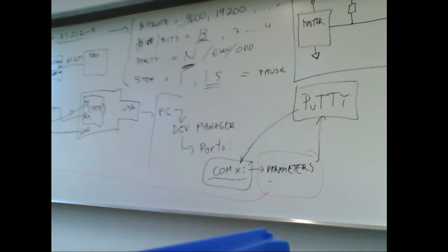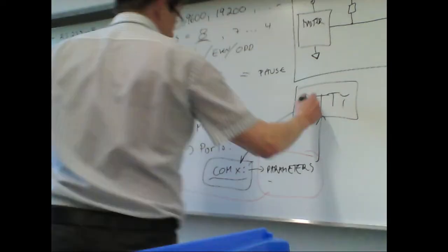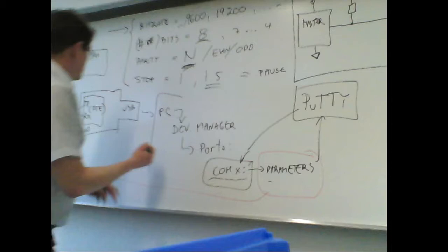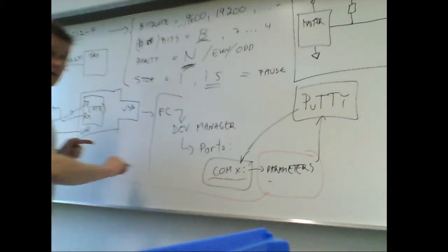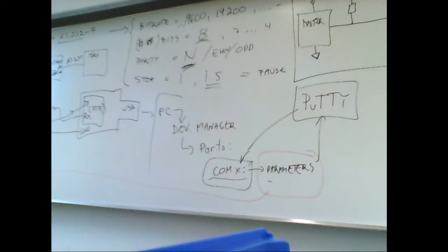Basically you type here A, your device should reply with an identification string. Simple. And that should show up on your terminal. Okay? And S means that it returns one sample from ADC, actually ADC and one wire. Okay, I need to modify that a little. Where's my exercise 4?